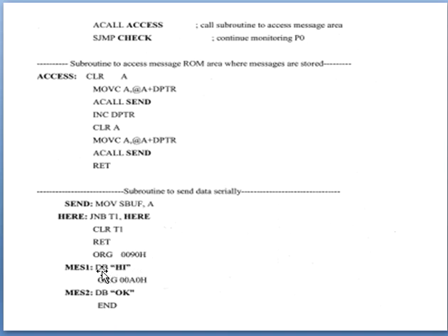This is define byte. So this MES1 is a variable that will be defined with the bytes of this HIGH string, so that will be assigned to MES1. Wherever MES1 comes, that will be replaced by this HIGH. This is just like an equate. So at the 0090h location, we are loaded with the HIGH value.